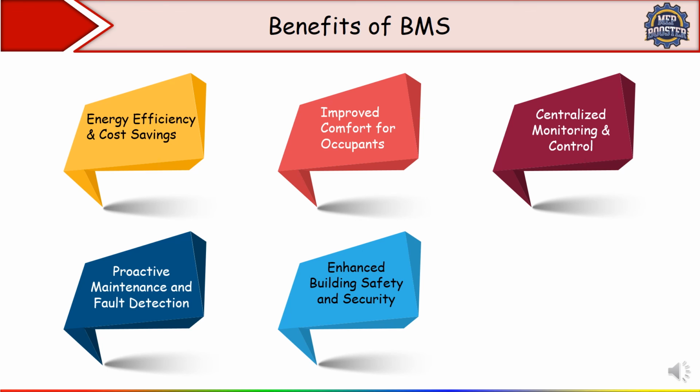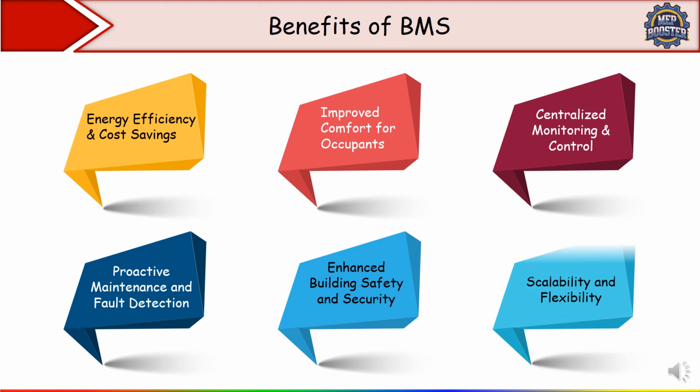And the next one is what? The BMS integrates with fire alarm, CCTV and access control systems to enhance emergency response and building security. Okay, for example, in the event of a fire, BMS shuts off the AHU, activates the pressurization fan for the stairwell and unlocks emergency exits automatically. So this is the benefit.